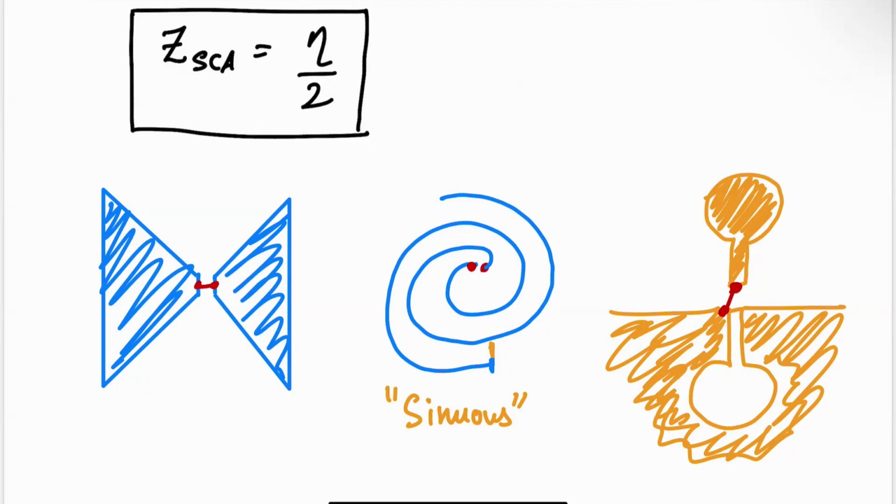So in those cases, you need to think about broadband techniques from a different point of view, and we'll do that. So in the next class, we'll look at other broadband techniques, other bandwidth enhancement techniques that don't rely on just planar structures. Okay, so we'll probably stop here. It's a good place to stop. Just to review, we essentially did a long proof of Babinet's theorem. Then we looked at what complementary antennas are. And we also looked at the end, what self-complementary antennas and essentially frequency independent antennas are.